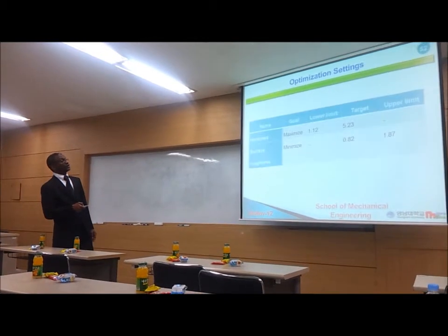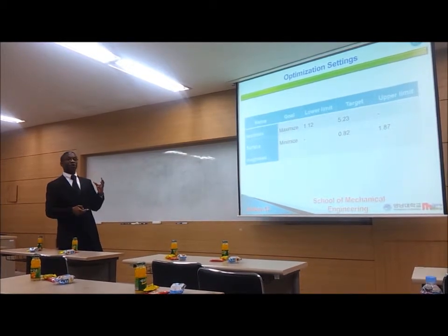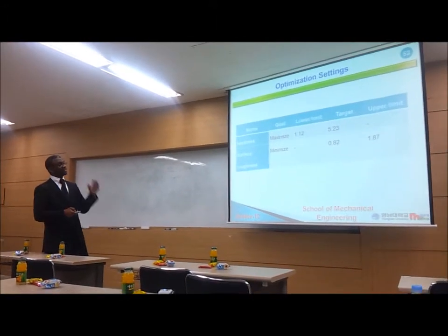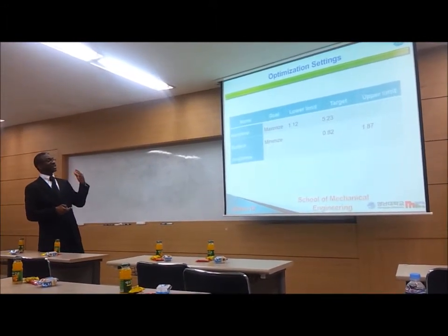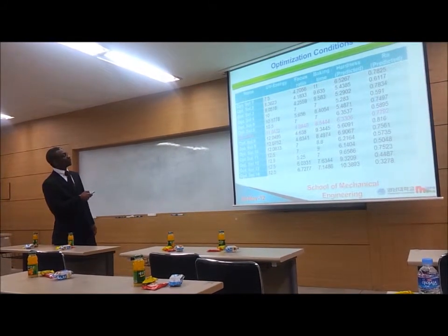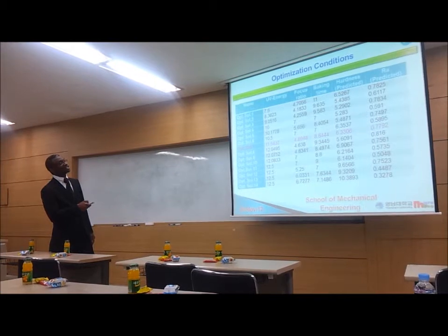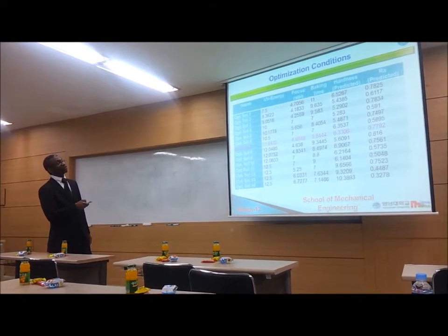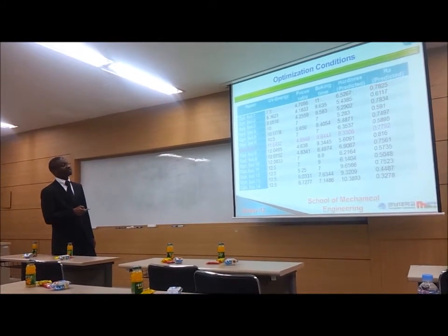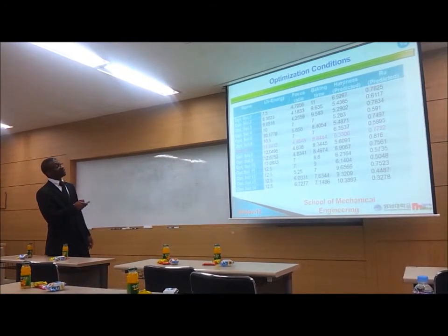Then I had to optimize the process to see what optimal condition we can use to fabricate the mask, and with which parameters. I set the minimum hardness of the mask I need and the surface I want. Then I realized we can use those parameters. For example, if we set this condition, we are supposed to have a hardness of around 6 HV. We use a micro Vickers tester to measure the hardness, and for the surface roughness you have to use a non-contact method. So if we predict with our empirical model, we can have those data.